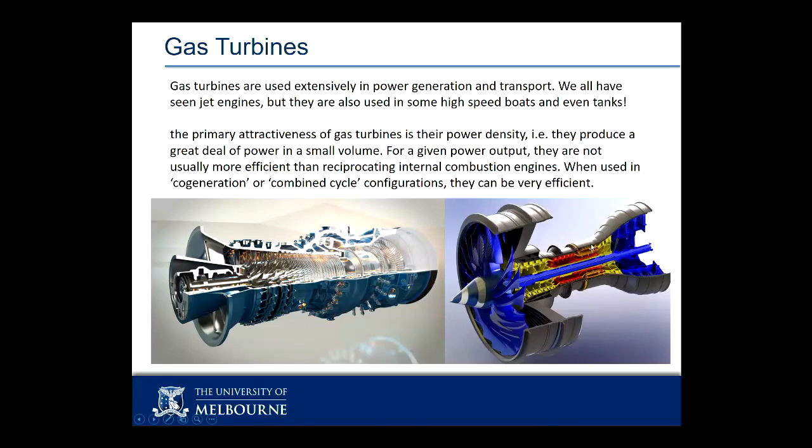This is an aviation gas turbine. Its primary job is to make thrust, to push air out the back with higher momentum than what came in the front. And most modern GTs have a great big fan out the front, effectively a propeller, and the gas turbine just takes part of that air. So if we compare the yellow bit here and everything from here to here, these are the compressor stages. My compressed air then bends around and comes down through here, and I put my fuel in and set fire to it here. And this is an annulus all the way around the GT.